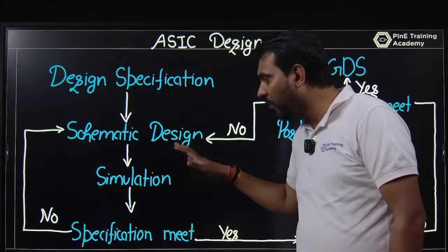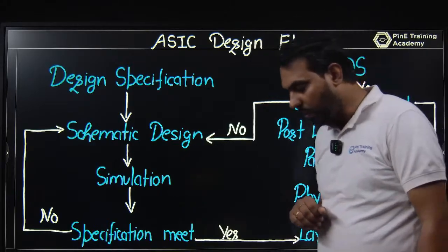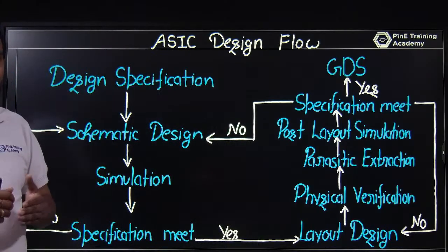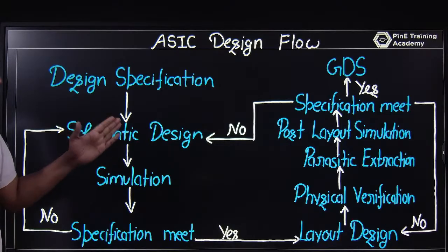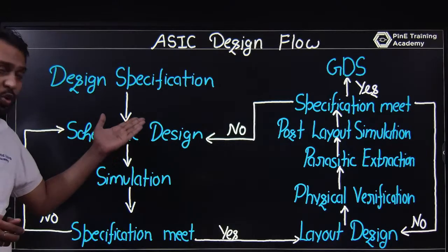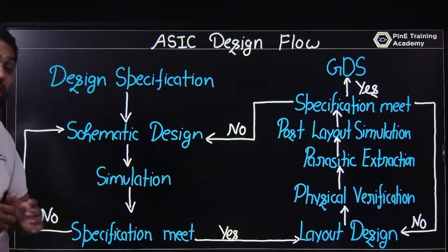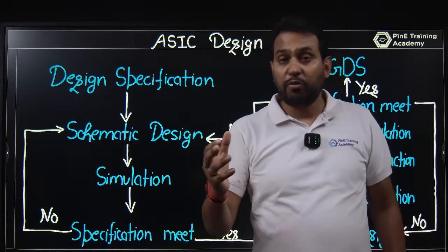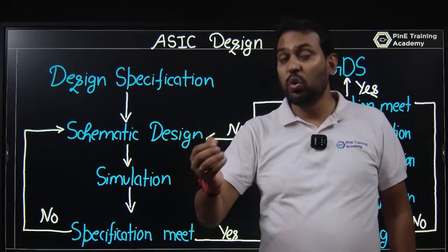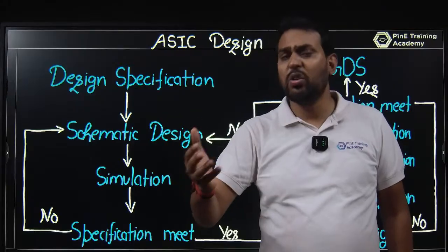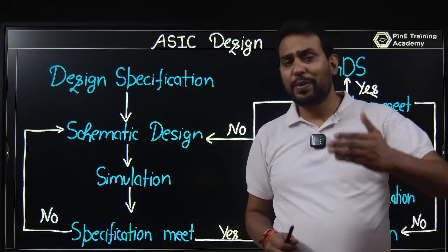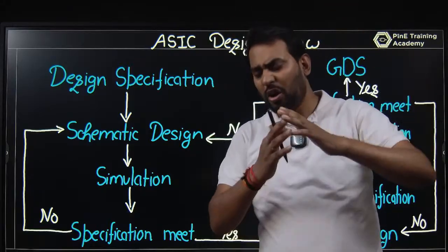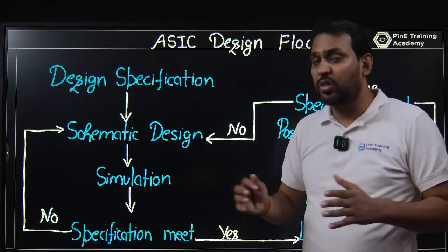After the schematic editor window you will go for simulation. Simulation means you are simulating the design. Let's say you have a CMOS inverter, and you simulate it. In a simulation you have a DC analysis, an AC analysis, a transient analysis, a lot of analyses. Just like in LTspice we have DC analysis, transient analysis, AC analysis, stability, operating point, a lot of analyses you have.